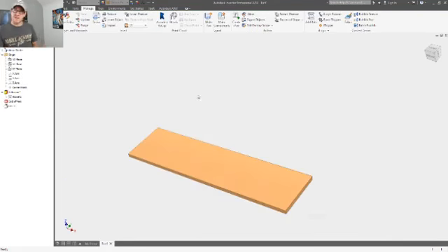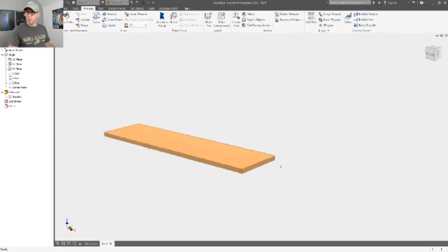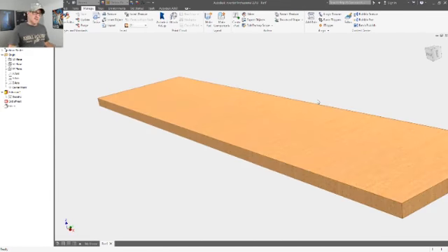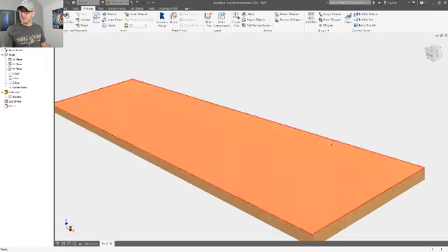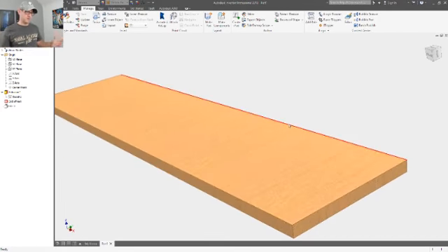So let's say this is a strip of wood, and when I'm looking at this, because of the way I built my model, the material isn't going the way that I want it to. And there's a couple ways to change this. So a really neat way to do this is if you want to change individual faces. So if you change the selection to face and edge, so I'll change my selection to face and edge.